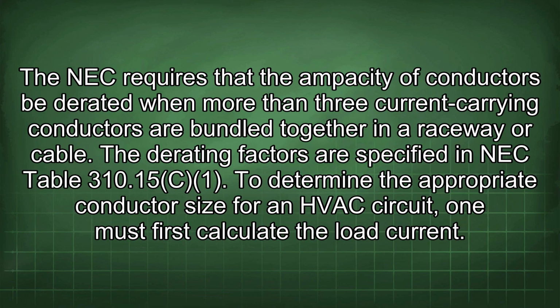The NEC requires that the ampacity of conductors be derated when more than 3 current-carrying conductors are bundled together in a raceway or cable. The derating factors are specified in NEC Table 310.15.